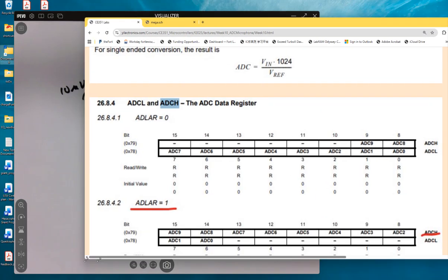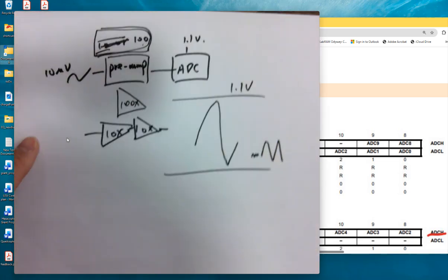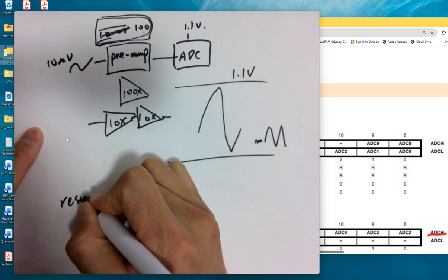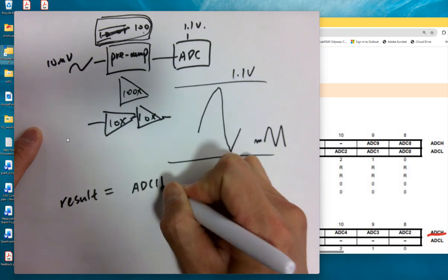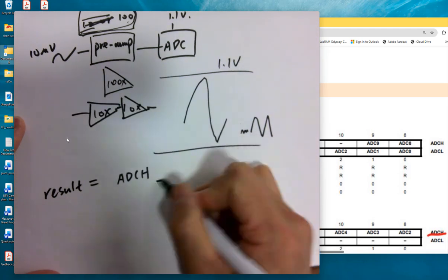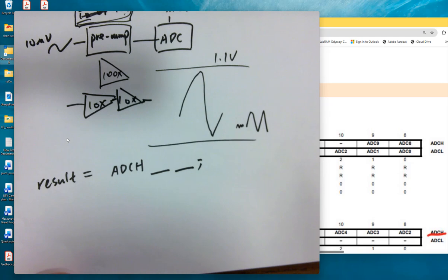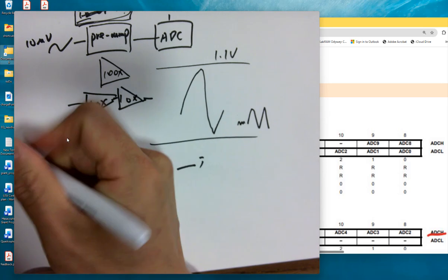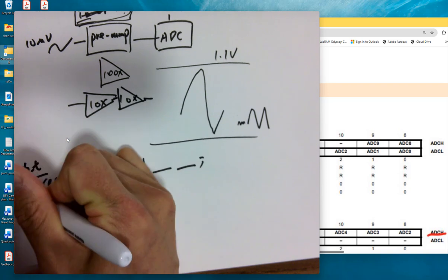Very quick question. After the conversion, the ADCH register will hold 2 bits. However, you don't want to directly use these 2 bits. You have to do this. Shift to where, by how many bits? And this has to be what? Unsigned int 16 type, right, for the result.